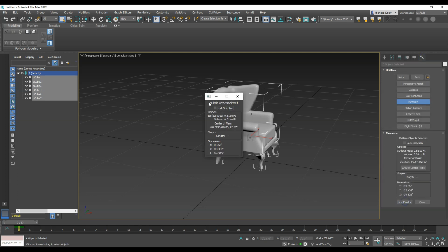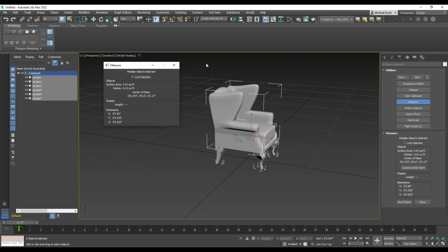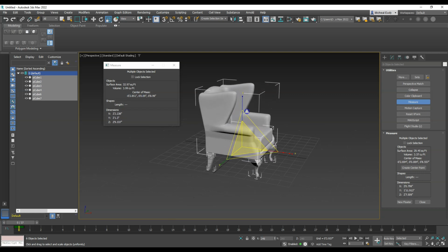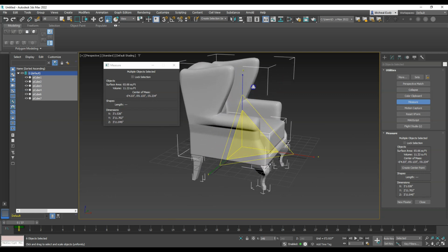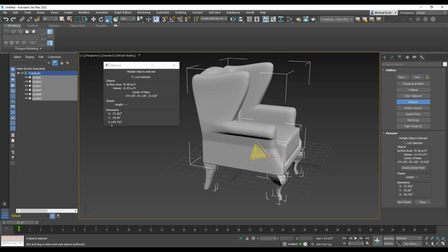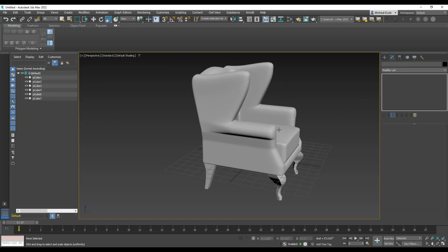So first thing I have to do is look at this stuff, and when I get them from students and I pull them in, this thing's 4 inches tall, so there's a problem. I don't know if they're not being taught how to model to scale, but especially when you want to transport this from one software to another, it's got to be correct size. So I'm in Max, and Max is set to centimeters, which is what Maya is set up to also. I'm not sure why this student's work is so small, but I get this a lot. People don't measure their stuff.